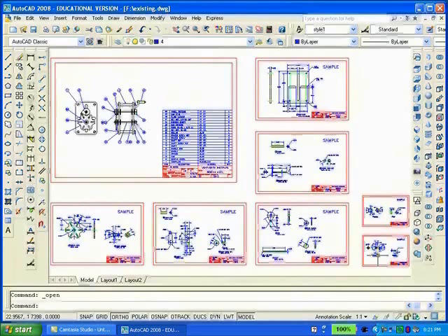Finally, when a drawing has to be plotted at 1/2 scale, it would require a dim scale of 2, whereas a drawing to be plotted at full scale, 1:1, only requires a dim scale of 1, which is the default. However, plotting at 1/4 scale would require a dim scale of 4, and so on.